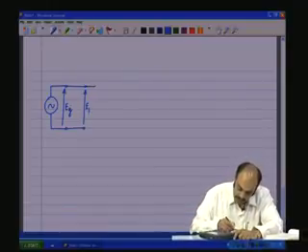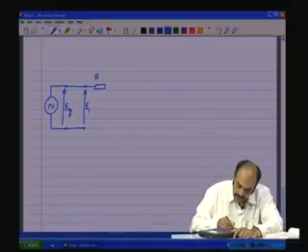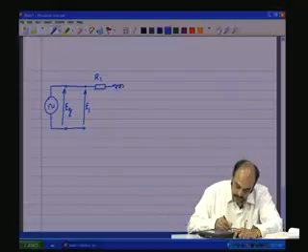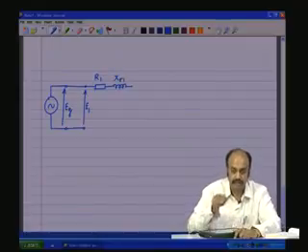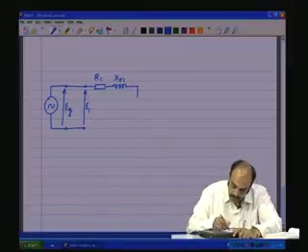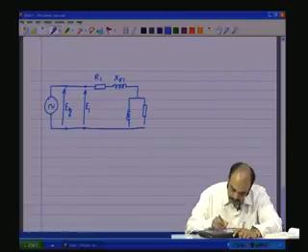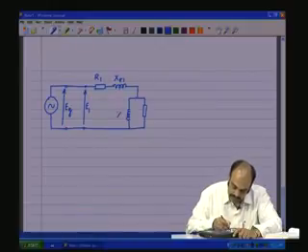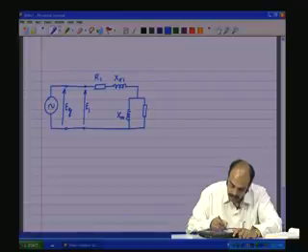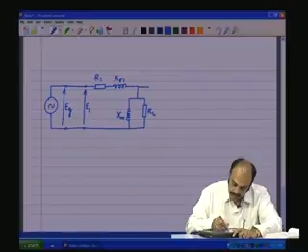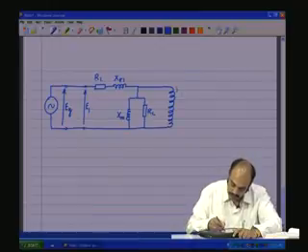Now, from the primary side terminals, if we go, you have first R1, the winding resistance, and then we have an inductance which is going to give an inductive reactance, the leakage reactance on the primary side, and then further going down we have two components that we discussed in the last class, which are the core loss component and the magnetizing inductance component, Rc and Xm, and this goes into the primary of the ideal transformer.